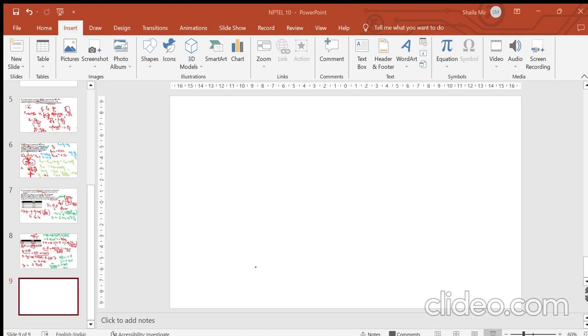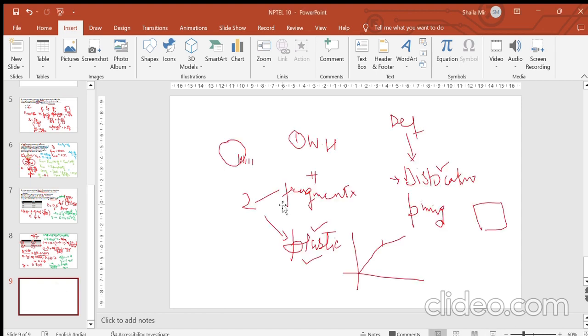This higher plastic deformation is favorable for powder metallurgy, because if it is deforming plastically, then there is annihilation of the voids. There will be a loss of porosity in the material, so you will have higher strength and higher density. So dislocation is important when you are talking about metallic materials. They always have dislocations present in them, and that helps them achieve higher strength.